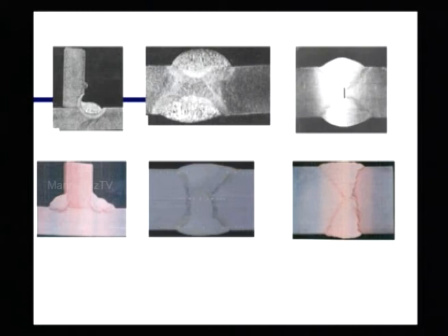This macro here is even done in a flat welding procedure, and as you can see, it is a very nice macro. No undercuts, very shallow weld. Here is also one very thick plate, also a very nice weld, and as you can see, no excessive reinforcement of the weld.